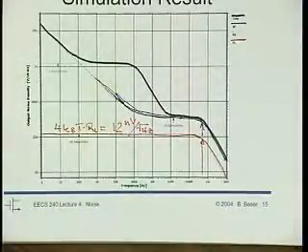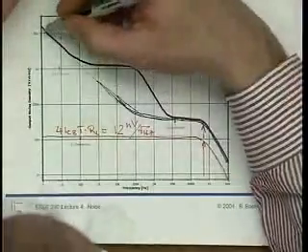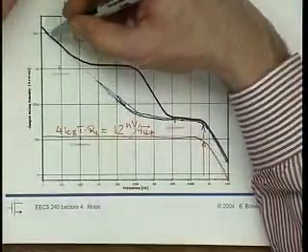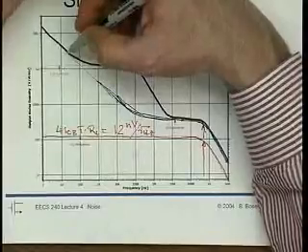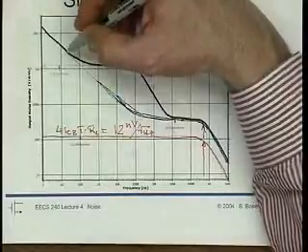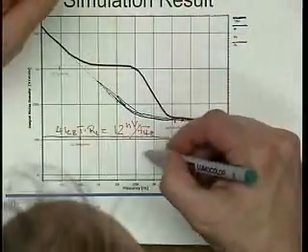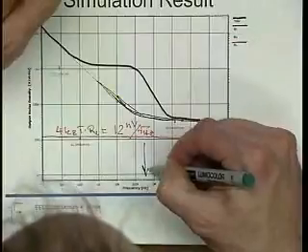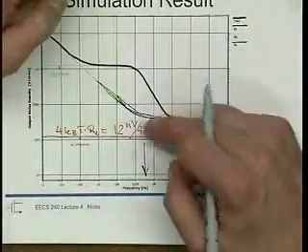Now, if you want to synthesize flicker noise and you don't have it out of your transistor, then it's a little bit of a question how you do that, right? Okay, but at very low frequency, of course, the MOSFET again dominates, because it is the only flicker noise contributor in our model, at least, and its 1 over F noise corner is somewhere around 300 kilohertz or something like that, right?